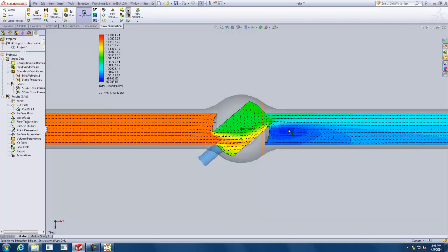And now we're looking at the pressure contour. All right, so the color contours are the pressure, and the vectors there are still the velocity vectors. So now you have two pieces of information shown at the same time. So we got this high pressure up here. All right, see a big pressure drop here from, say, orange to green, from around 113 kilopascals to green, which is 107 kilopascals. And we have this low pressure region in the middle of the vortex where we expect it to be. So it's a lot of information we can see now.